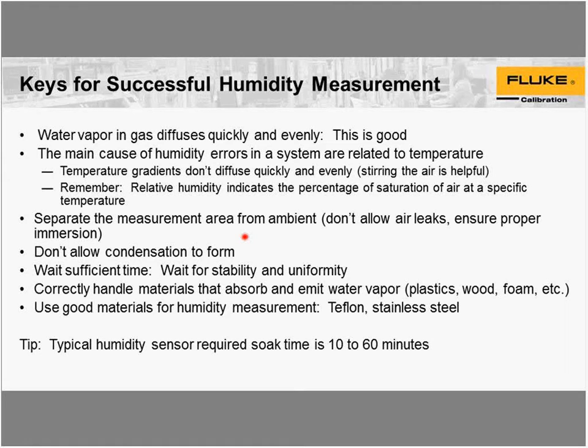Allow sufficient time. One of our partners on this project, who has spent his career working in electrical measurements, said waiting for humidity measurements to stabilize is like watching paint dry. He's used to the electrical world where you push a button and within maybe milliseconds or a few seconds, your measurement's stable and ready to go. So be prepared in humidity to wait.